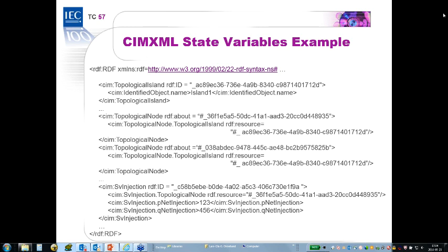although if you have a load associated with bulk power, that would be a major industrial load. The more normal kind of load actually comes because you have this boundary to a sub-transmission, and then there is more detailed load and injection data on the sub-transmission part. And if you want to reduce away the sub-transmission, you reflect the load up to the boundary. I'll talk a little more about that later.